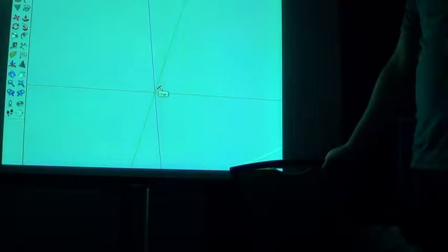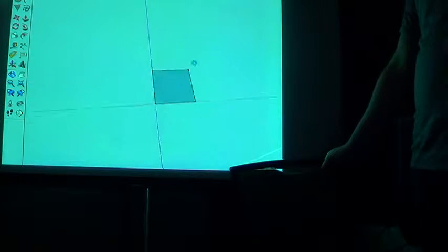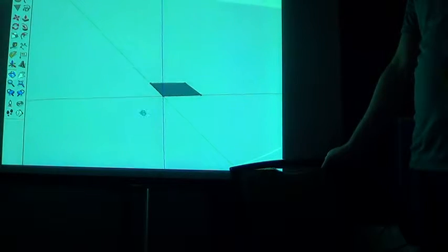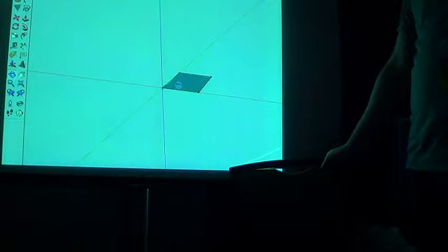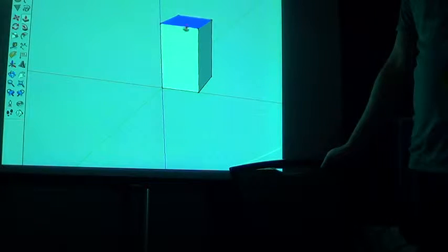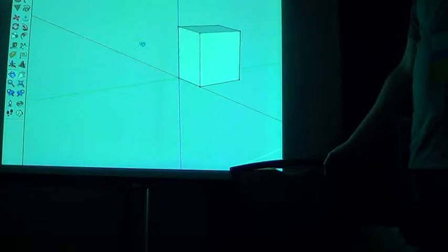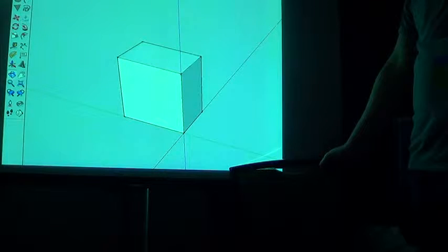You're basically putting together two-dimensional shapes. So here I've got just a rectangle, which has absolutely no depth whatsoever. So the 3D printer would not know how to print this. If you had an open-faced cube, the same thing would happen. So let's go ahead. We've got a rectangle there. We're just going to extrude that. There's a push-pull tool in SketchUp. So now we have a three-dimensional box, which looks awesome. And this would print fine.